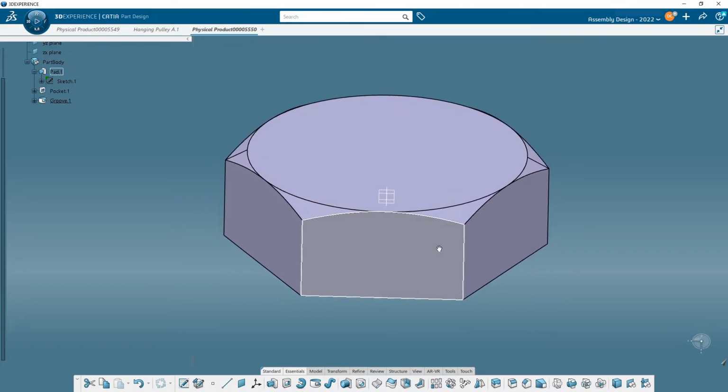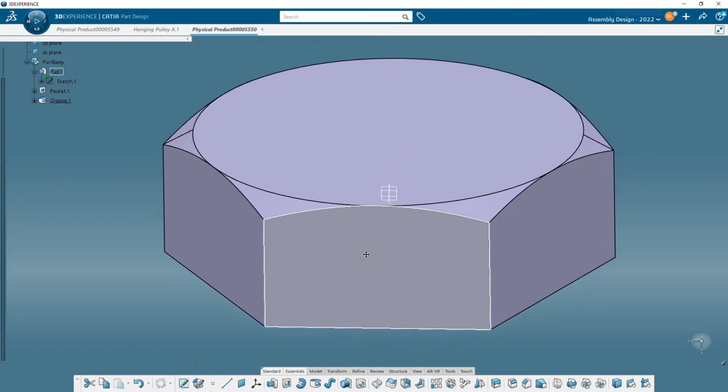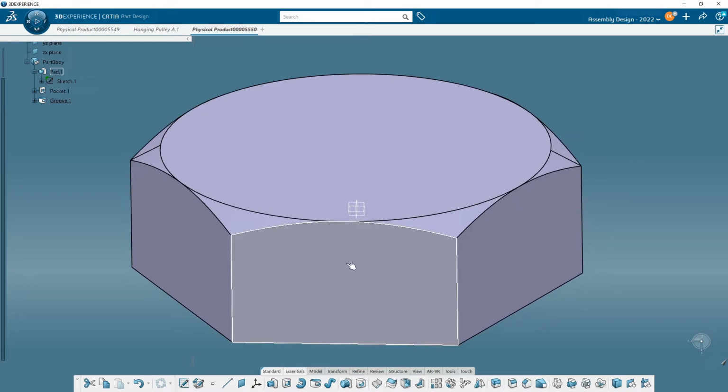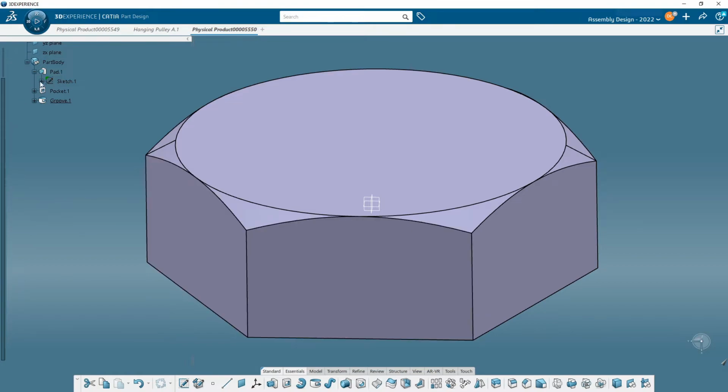Here, this is a perfect example of a different type of error. It is functioning. It's not red. It's not trying to do an update. It believes that everything is fine. I look through the tree here. Everything's fine. What makes the hole? Well, that pocket makes the hole, and you might have just seen what's going on here. Inside the sketch here, you could open it up like I just showed you. Everything looks fine.